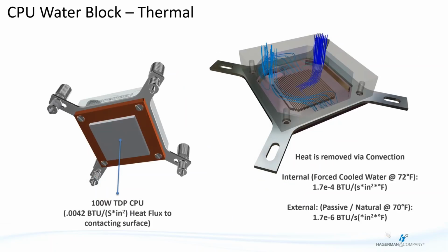Chilled water is forced over the copper block through some tortuous path, rapidly removing heat. In this case, an acrylic block contains the flow and directs it through some fins integrated into the block. Nastran In-CAD does not simulate fluid flow. Most FEA codes are either structural or CFD, not both. Autodesk does produce a great CFD tool, which is how I got the image you see on the right. In structural FEA, we typically apply coefficients to the surfaces which contact fluids in real life, in order to approximate their heat transfer effects. And that's what we're going to do today.